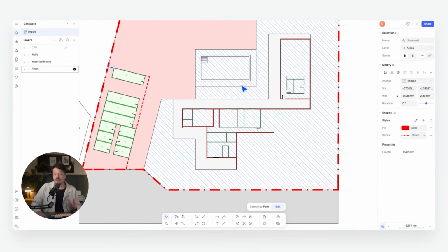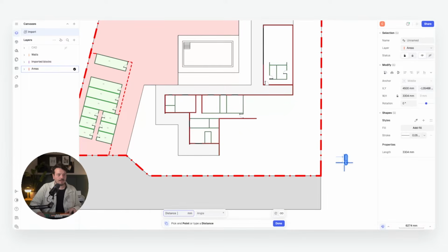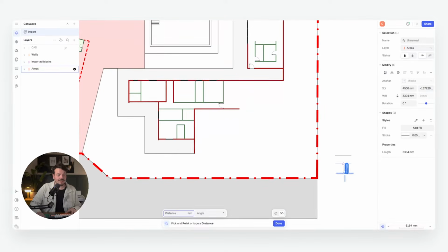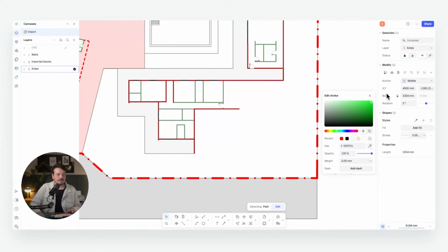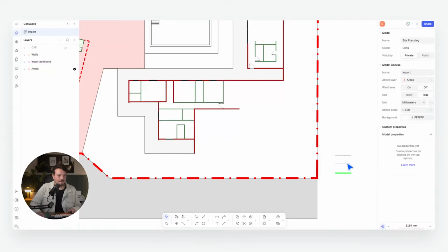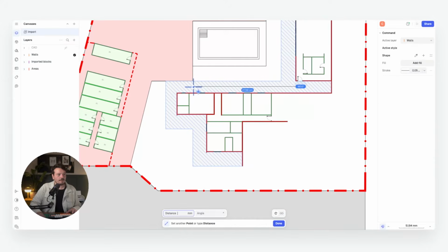And then we could have a few different other line types. So for example, we might want to indicate where our temporary water is, our temporary electric, and a health and safety line. So one that shows a clear route, a safe route for people to move through. So let's say our safe route is in green. Our water route is in blue, which makes sense. And our electricity line is in, let's say, orange. We can just plot those on the drawing.